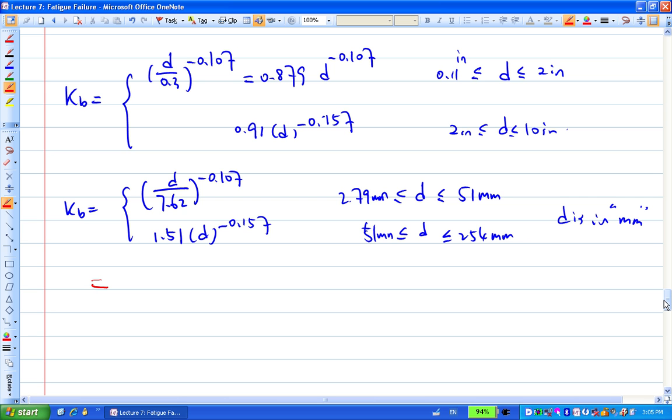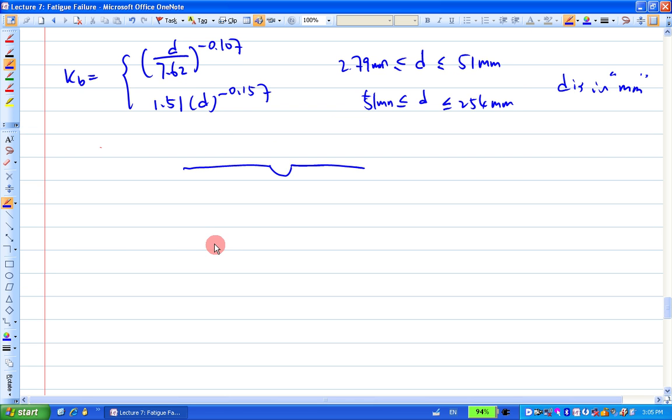In reality, you don't have the same loading conditions or the same kind of rotating condition as the lab, so we have to modify that a little bit. I'll draw one scenario you may encounter in the future. You may have a shaft with a notch in the middle. If this shaft is rotating and subject to constant bending, then you choose this as the D in the formula.